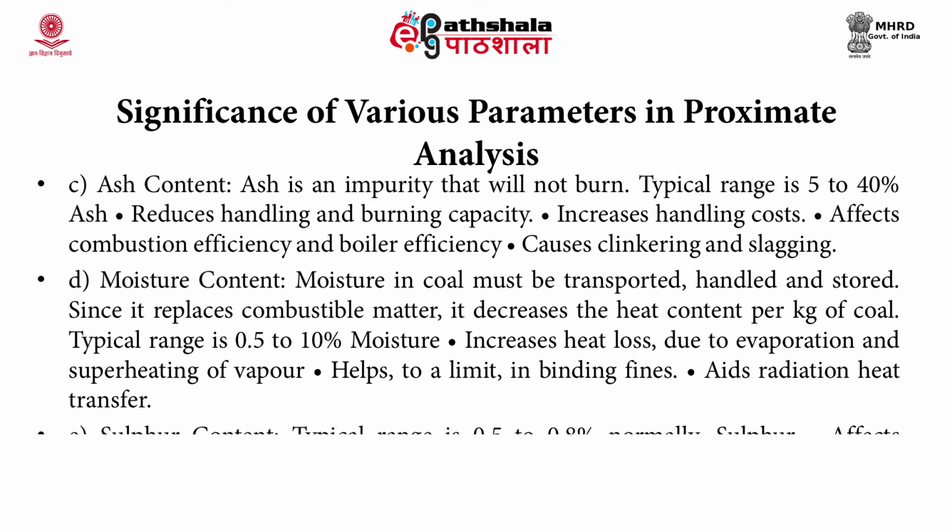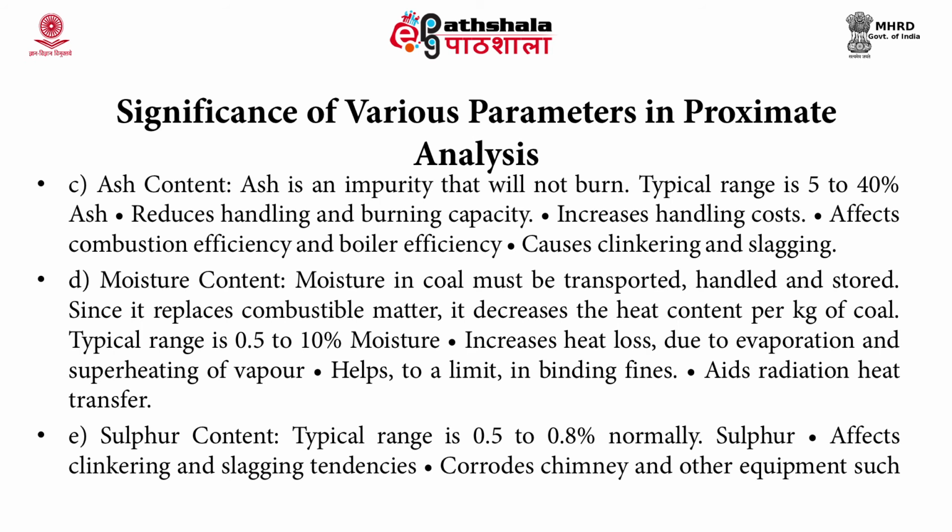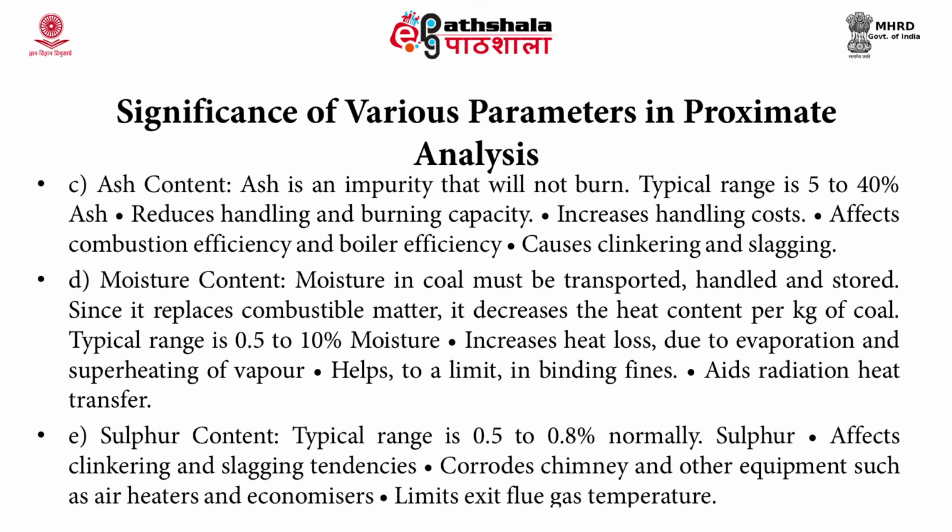Sulphur content affects clinkering and slagging tendency. It has a slagging tendency. It corrodes the chimney and other equipment, and it limits the exit flue gas temperature.